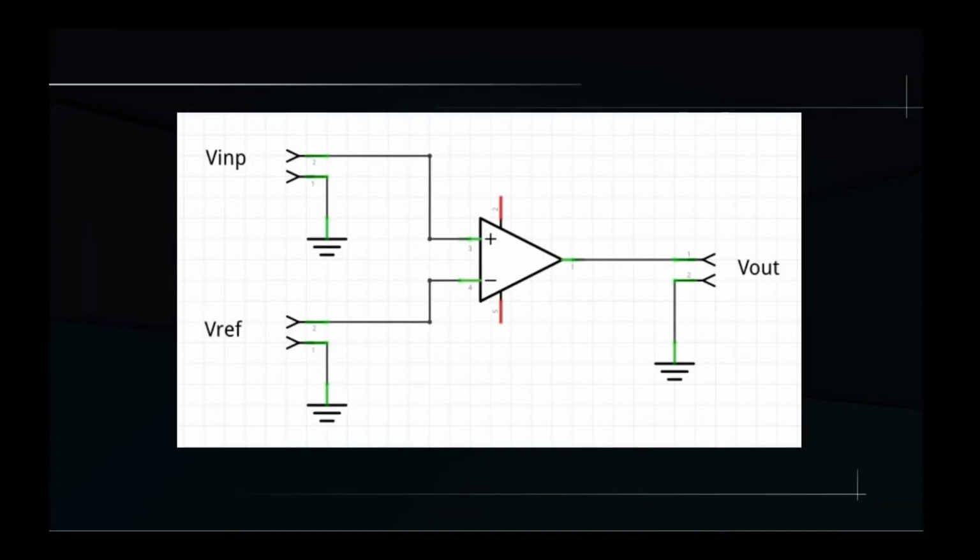And here is the other simple circuit that can be created with an op-amp. There it is, nothing else. Not even the negative feedback connection. Well, what's going on here? Simply put, with this circuit we want to actually exploit the extreme gain of the op-amp, bringing it into saturation. That's why there is no feedback.